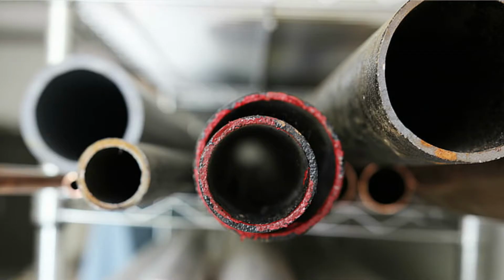So bar stock also has another cool option, especially in the round bars, where you can get different surface finishes attached to it right from the steel mill. One of the popular ones is chrome plating. Chrome plating is great for surface hardness, and this is a material that's widely used with cylinder design and with pins. Now let's move on to tube steel.